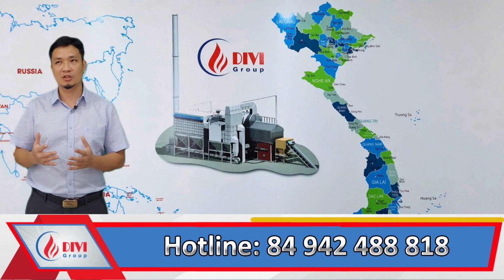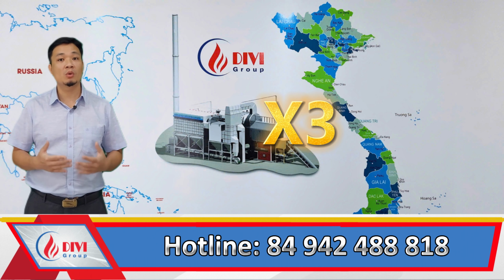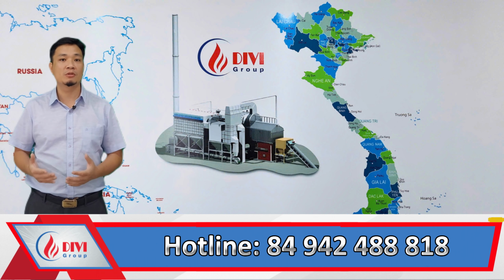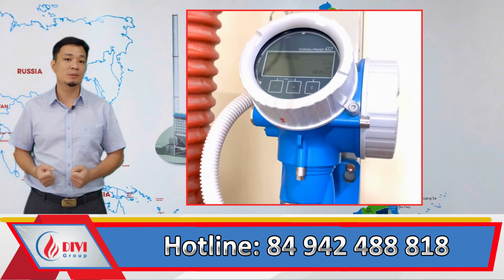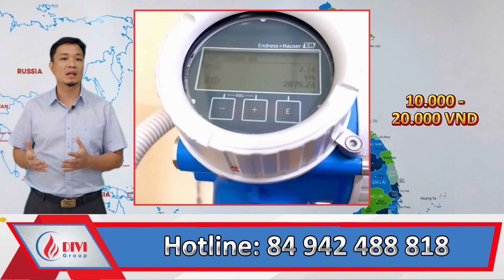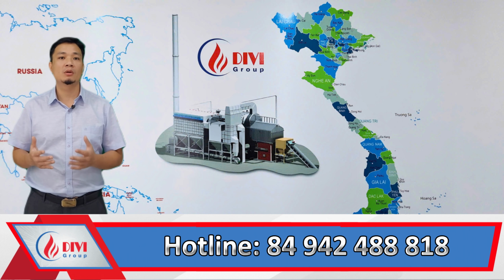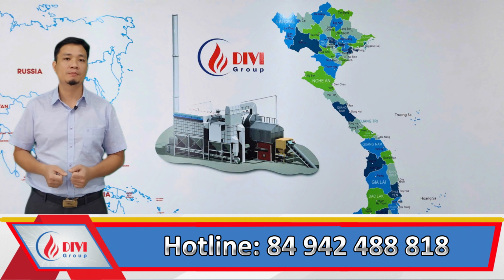This means the fan's energy consumption can triple when using a fluidized bed compared to a regular boiler setup. Based on DIVI's field experience, using the fluidized bed material adds approximately 10,000 to 20,000 VND in electricity cost per ton of steam. However, this added cost is relatively minor, especially when burning low-grade fuels that require a fluidized bed material to achieve optimal combustion.